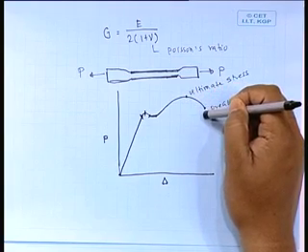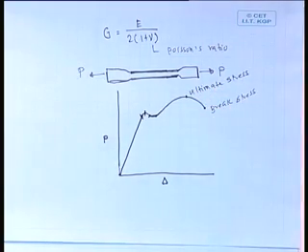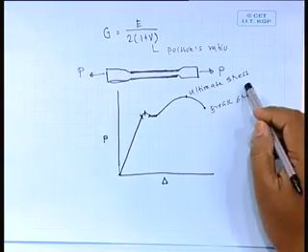Now, there might be one question, why is the load suddenly decreasing, because in the machine we will try to pull the specimen. So, up to ultimate stress it will go on increasing. Suddenly why? Because elongation will be more, but your load level will come down.